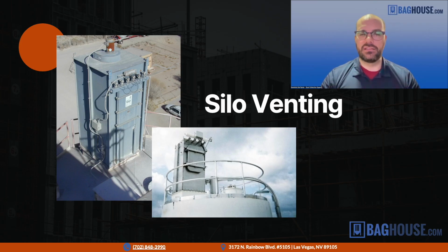Now, moving to the last kind of collector we'll discuss, which is when we have just a silo to vent or enclosed space, we often use what are called bin vent dust collectors. So here you see a picture of one. Bin vent dust collectors are basically just baghouses that have the bottom section cut off, have the hopper section removed. So that's why they look like two-thirds of the baghouse. Everything else is exactly the same. They have the same filters, the same cleaning mechanism, the same controllers.